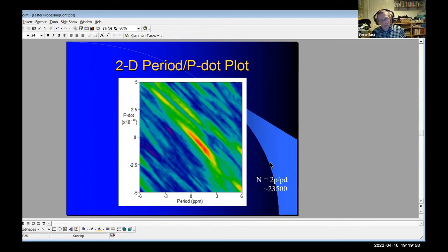At the frequency you're at, you don't see atmospheric changes in polarization that might be. Actually, if you looked at my data, the quality of it is very high. The reason it's high is that I took this data last October, from about 12:30 in the morning to about 4:30. So it was right in the night time where everybody's asleep, nobody's using washing machines, no one's mowing their lawns, nobody's doing any DIY, nobody's running their computers, they switched them all off. And I had virtually no RFI in that measurement.